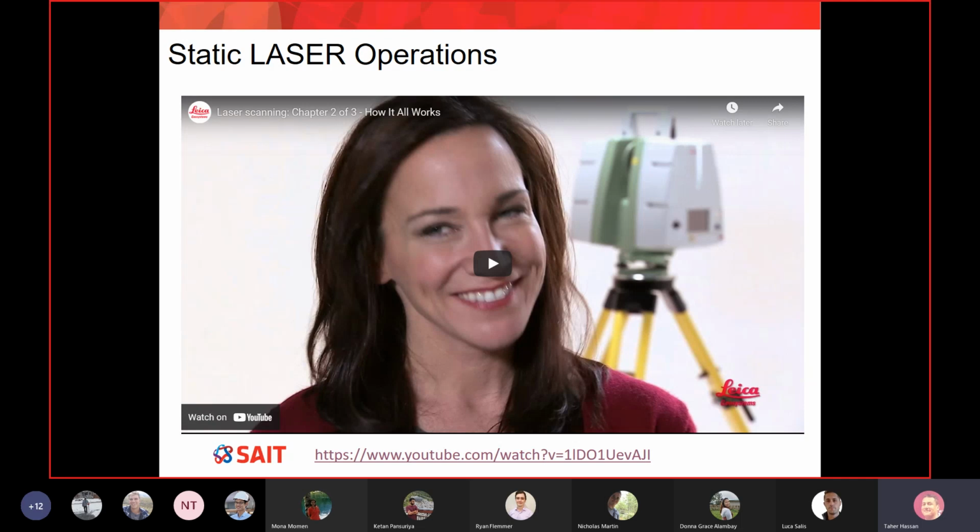Okay. So that's one thing I wanted everyone to understand and recognize, that a laser scanner is pretty much, in theory, using exactly the same set of equations that we went through in the beginning of the semester, but it's a continuous scan, not a specific point. And that's why it's not selective. For example, if my client asks me to survey the manholes and I'm using a total station, I will be surveying only manholes.